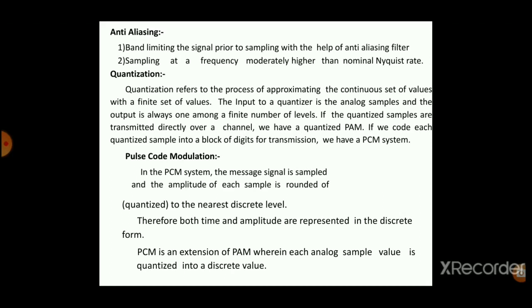Anti-aliasing: band limiting the signal prior to sampling with the help of an anti-aliasing filter, and sampling at a frequency moderately higher than the nominal Nyquist rate.